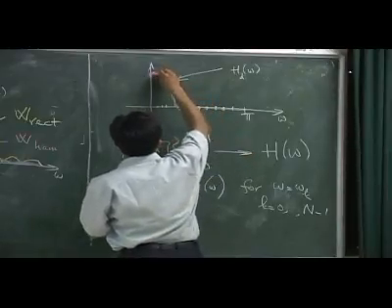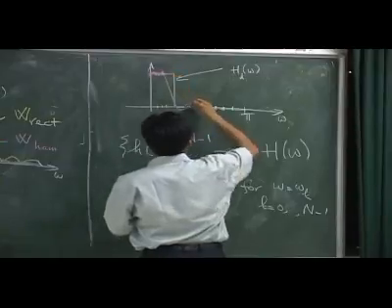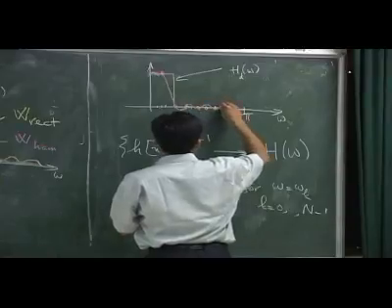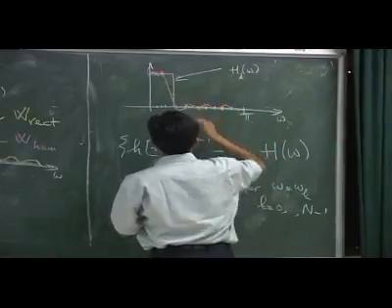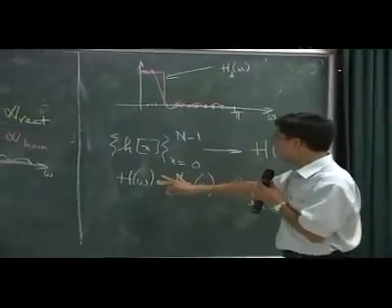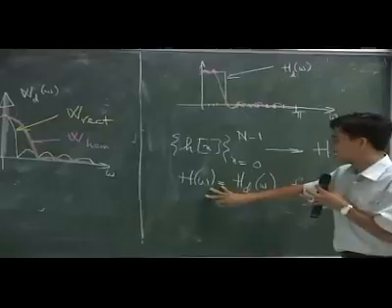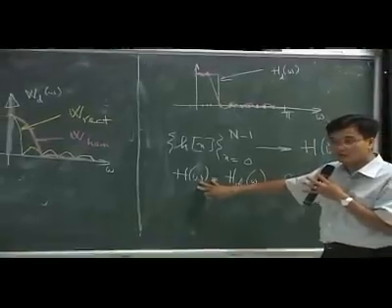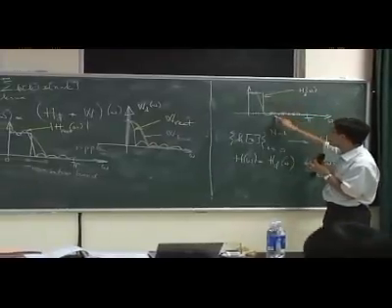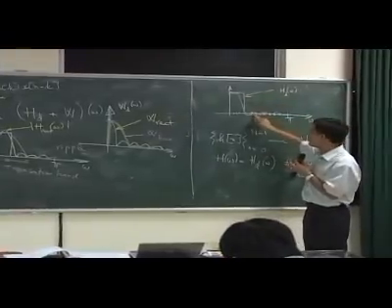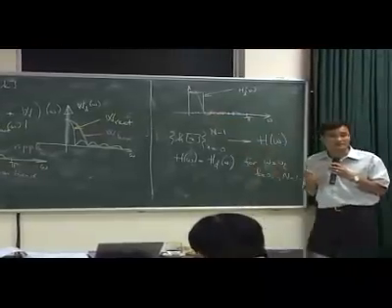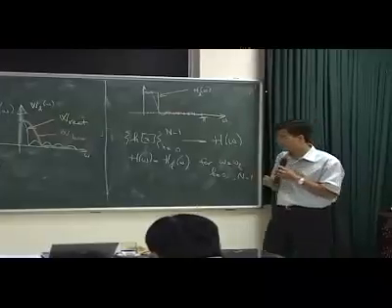These are the points where it crosses and matches the ideal filter. But in between, I have no other guarantee. I just hope that, because if this is a finite length filter, you can easily show that this thing here is a continuous function, so it is going to vary very continuously. So if it is okay here, maybe nearby is not too bad. That is the idea.